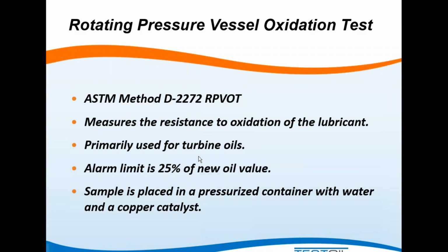A lot of times I'll get questions about, hey, this new oil scored 500 on RPVOT and this other oil scored 1,000. Is this sample twice as good as the one that was at 500? And the answer is not really. You can't really compare one to the other and judge its performance.